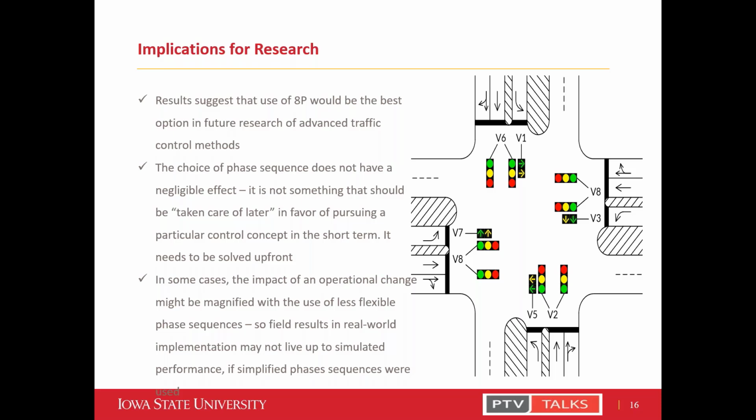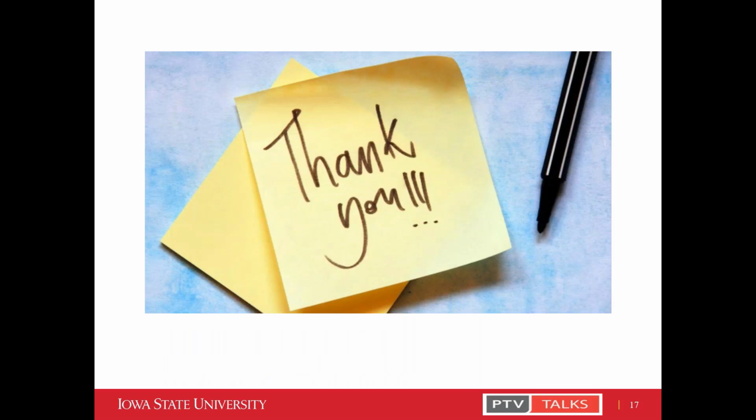And finally, in some cases, the impact of an operational change might be magnified with the use of less flexible phase sequences. So field results in real-world implementation may not live up to simulated performance if simplified phase sequences were used.